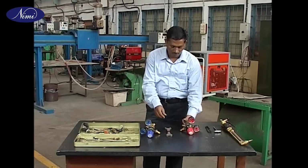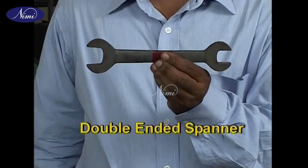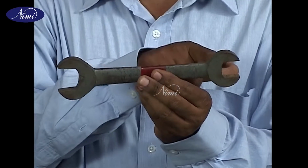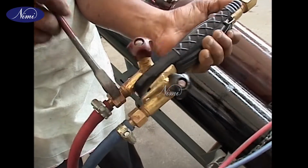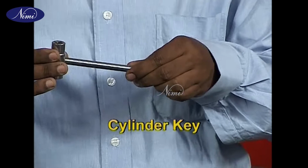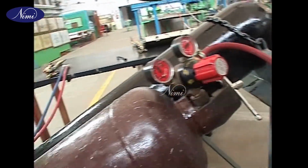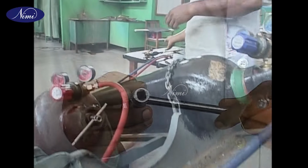Now let us come to the other tools. This is a double-ended spanner. One end is used for connecting the regulator to the cylinder and the other end is used for connecting the hose to the regulator. This is the cylinder key, which is used for opening and closing the cylinders.